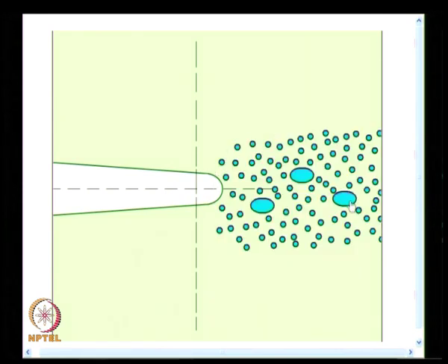The process starts here. Initially, the large particles break, then you have myriads of holes formed, they fail by micro necking, and the crack moves forward. And you see, when you have this micro necking followed by crack propagation, because particles are removed, you find the surface is not smooth, it has valleys and mounds. In fact, you would be able to see that at appropriate magnification in a scanning electron microscope.